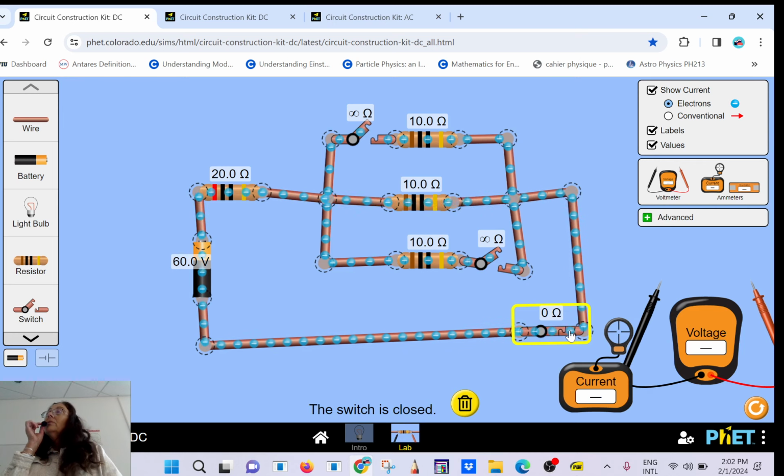The question to you is the following. You see here, the switch is not closed, the switch is not closed, okay? And you can measure the current here, which is 2 amps. How did you do it? How can we find that? We use Ohm's law. So if you just consider that circuit here, because you know the other ones are not closed, what's going to be the equivalent resistance here in this circuit?